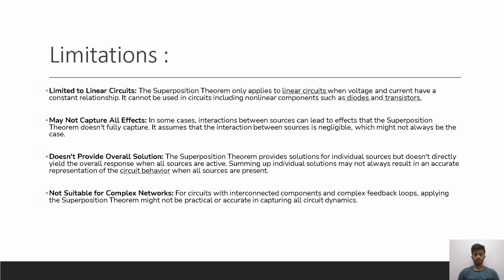Limited to linear circuits. The superposition theorem only applies to linear circuits where voltage and current have a constant relationship. It cannot be used in circuits including nonlinear components such as diodes and transistors. May not capture all effects. In some cases, interactions between sources can lead to effects that the superposition theorem doesn't fully capture. It assumes that the interactions between sources are negligible, which might not always be the case.